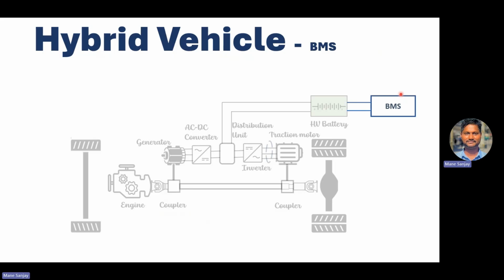The task of the battery management system is to ensure the optimal use of residual energy present in the battery. In order to avoid overloading of the batteries, the BMS protects the batteries from deep discharge and overvoltage, which are results of extreme fast charge and extreme high discharge current. So it also gives all the information of what is going on inside the pack.